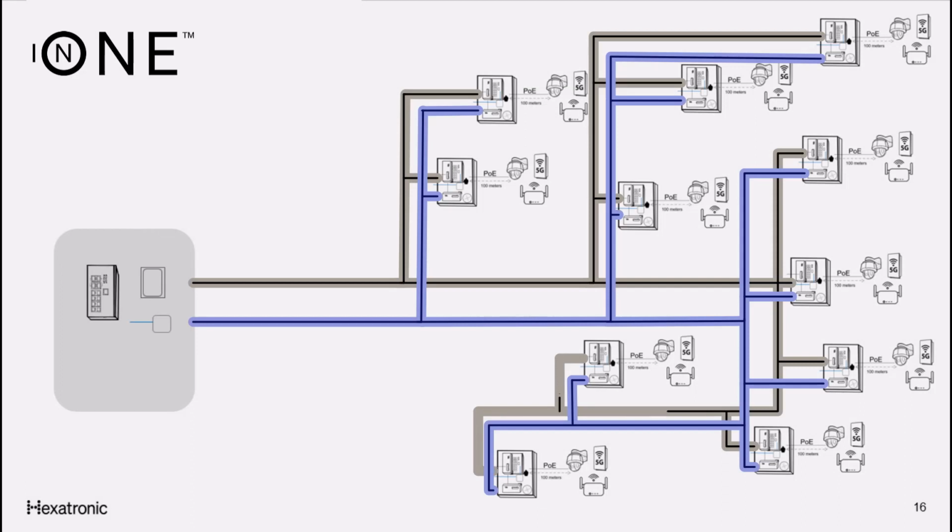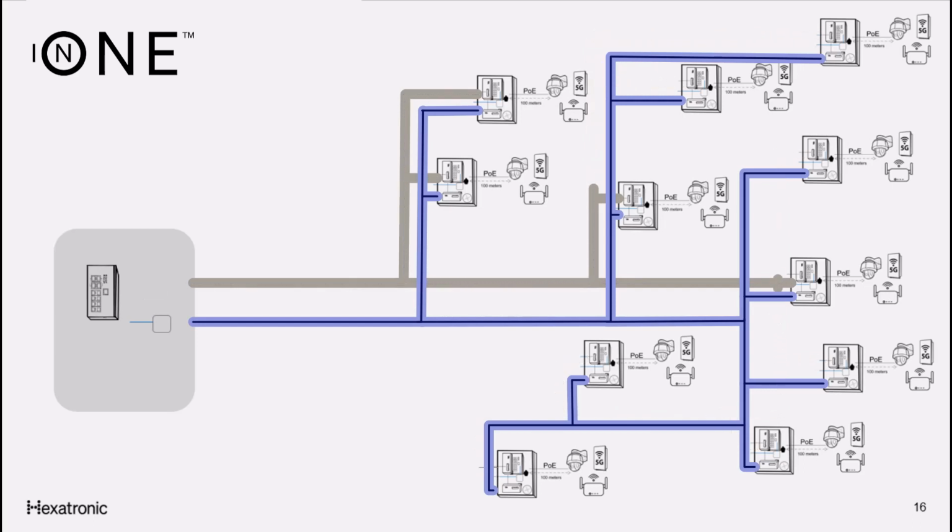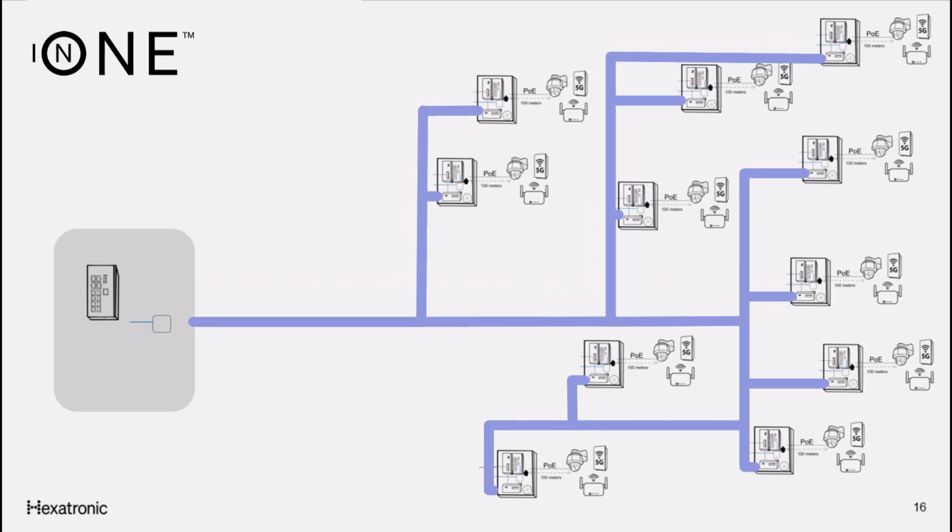process. First, let us start by removing the no longer needed AC cables, panels, and associated accessories. With AC cables out, there is no longer a need for the accompanying civil work either. Now, let us substitute the fiber optic cables with the in-1 hybrid power and fiber cables. Fortunately, these hybrid cables are only slightly larger than the fiber-only cables, meaning they can, in most instances, utilize the same ducts if you had them already.